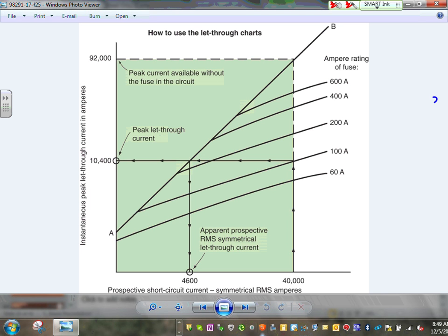So for current limiting fuses, guys, they take an interrupting rating of 40,000 amp, and they put the current limiting fuses, looks like 100 over here, and it kicks it back to this curve, and that will bring it down to 4600. You know what that means? A 40,000 amp short circuit will be seen downstream as 4600. Who cares? Now your VFDs and soft starts and PLCs are not going to burn. Major concept. So that's the heat.